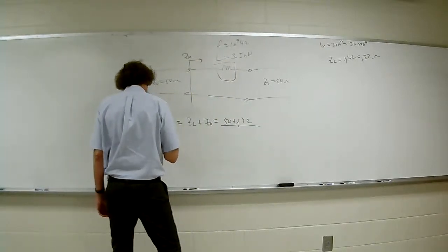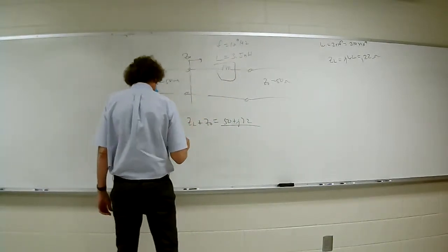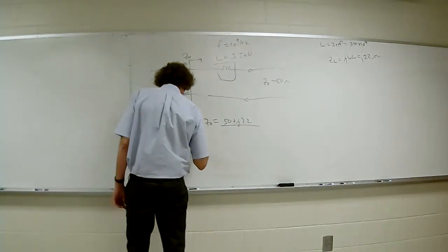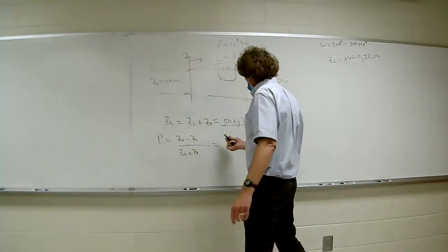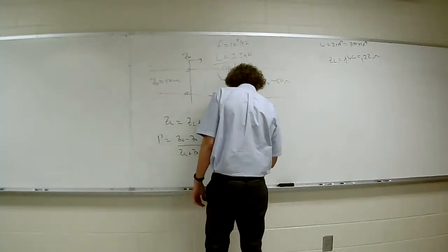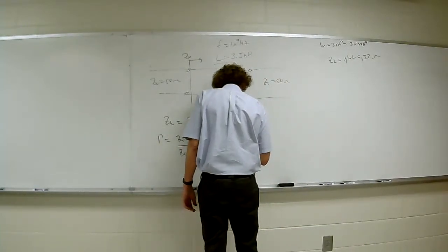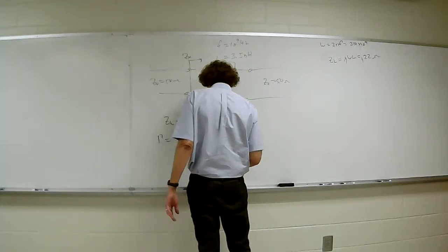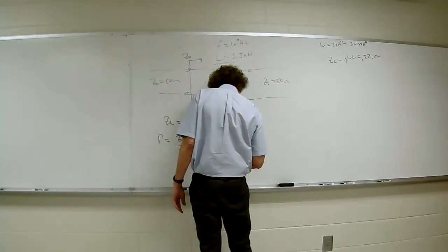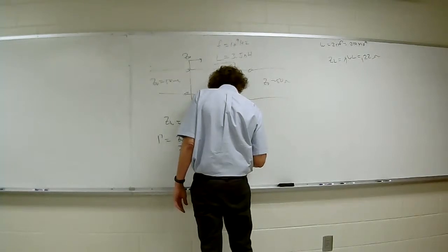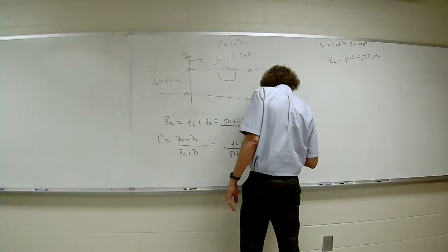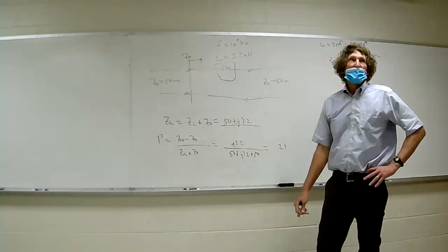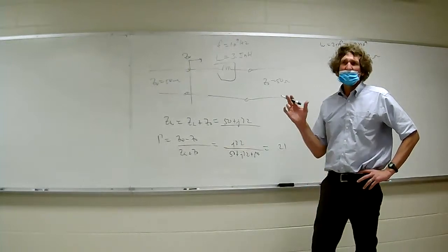Now, when we get the reflection coefficient, that's the impedance you're going into, minus the impedance you came from, over the impedance you're going into, plus the impedance you came from. And so that's going to be this minus 50, or it's just j22, over Zin plus Z0, which is 50 plus j22 plus 50. And I want to say that's 0.21, but I don't remember exactly, at about 33 degrees. Is that one?